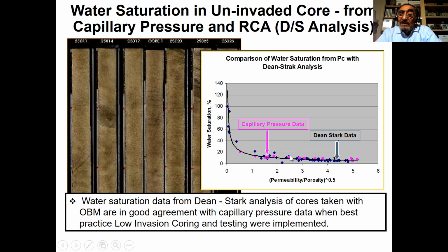You could see this is very important because that helps determine the remaining oil saturation in the reservoir and oil in place. You could see that most of the reservoirs had about 20-25%. This reservoir had 20-25% initial water saturation. So it's supposed to be a very uniform rock, but there is a lot of variability in it.